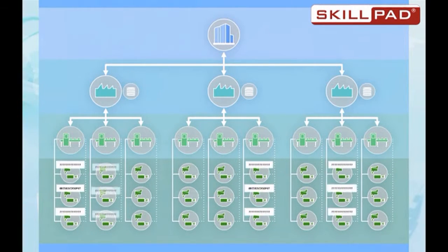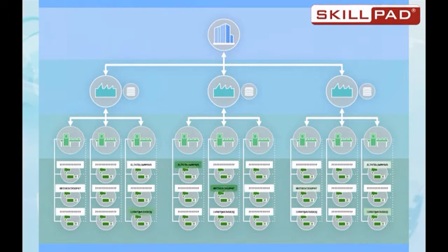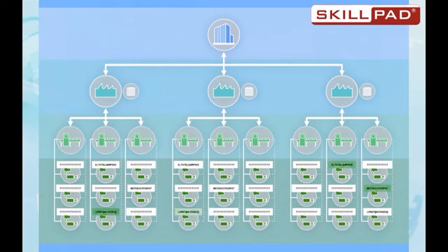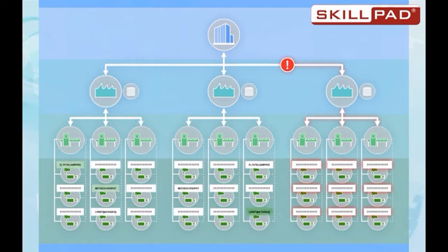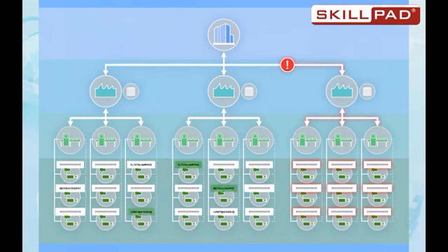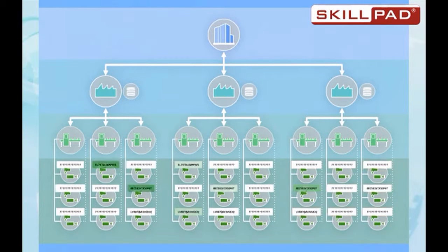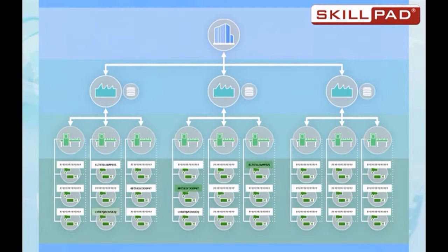A question often asked is why the numbers are not drawn down as needed from the enterprise level and used in real time. Well, if there was an interruption in the communication path, then the packaging run would need to stop and await further supply of serial numbers. This would delay the packaging process. As packaging commences, the serial numbers are fed to the correct line and issued to the printers.